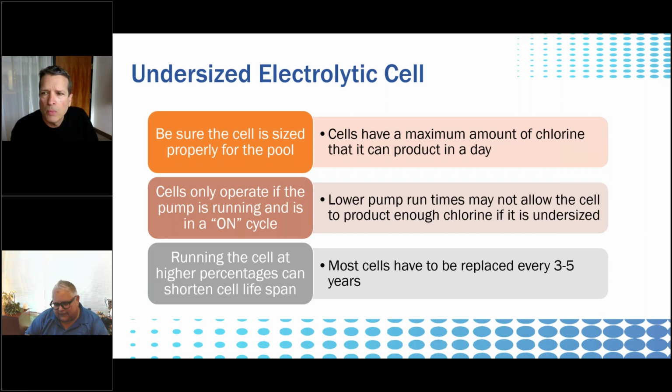The other thing with variable speed pumps in general is, if you're not moving water through the system, you're not filtering it either. And filtering is a huge element to properly taking care of any pool, including saltwater pools. So the lower you run it, the less turnover you have, which means less water moves through the filter, through a heater if you have one, through an ozonator or an ionizer or the salt cell or your chlorinator, anything you're using to put in sanitizer or to help with your water chemistry.